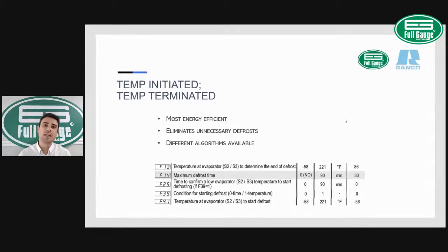So instead of starting the defrost on a cyclical time base, for example, 1 defrost every 4, 6, 8 hours, where you don't know if your system is calling for defrost or if the defrost is actually needed during those times, you normally start the defrost when your coil loses efficiency below 90%. That's when you normally start your defrost cycle.